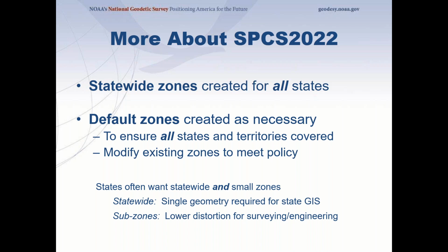for GIS projects going across the state. And in Hawaii, this will be a big help because right now, if they're doing any work in UTMs, the state's divided by 2 UTM zones and 1 island is divided by 1 UTM zone. So if they decide to use 1 UTM zone for the whole island, they can distort the other part of the island. So this will help take care of the distortion in the mapping for the GIS users.